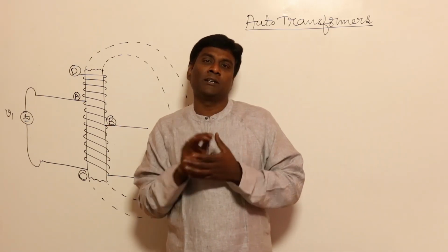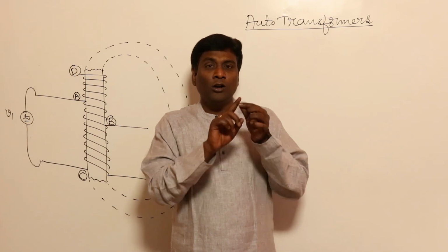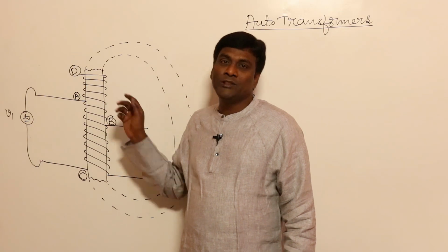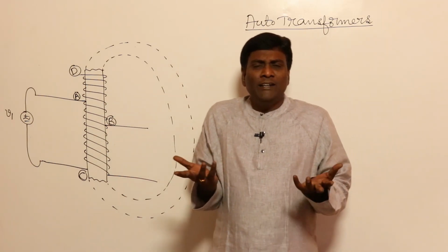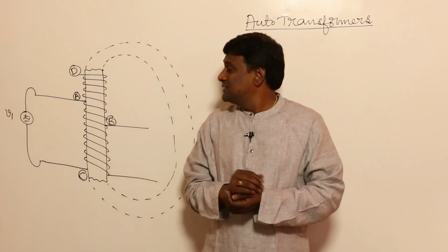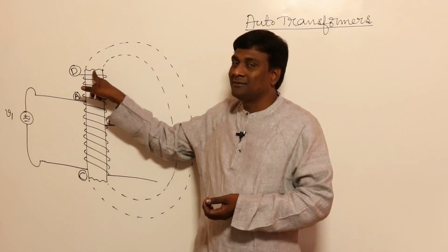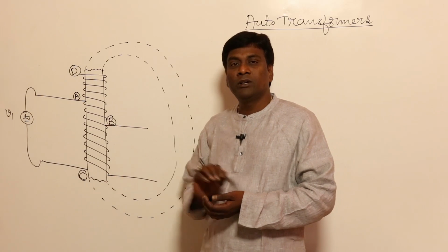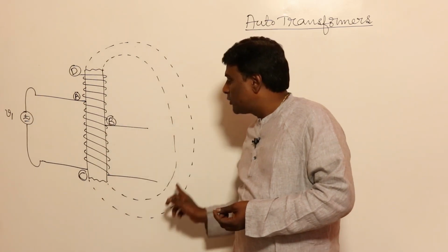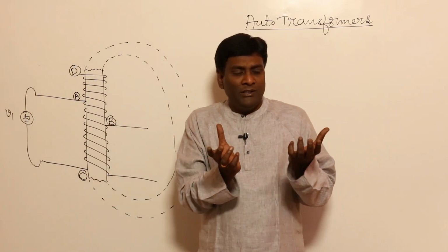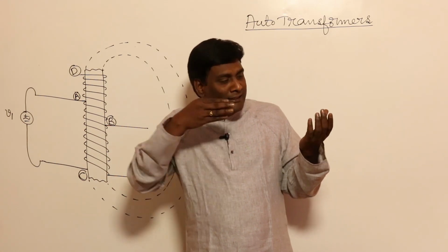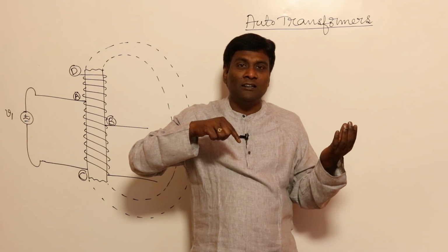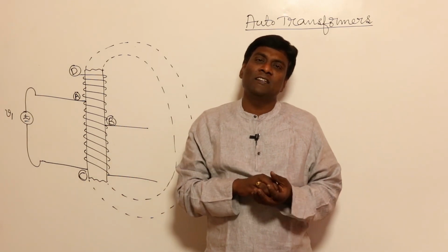Now if you come back to here, in auto transformer, what is the winding resistance? We are going to keep the winding with copper, so winding resistance is going to be less, but inside you are going to have iron. This iron rod has to be closed. If I think of the machines lab rheostat, and inside I insert iron and close the iron path, automatically inductance effects will be more.